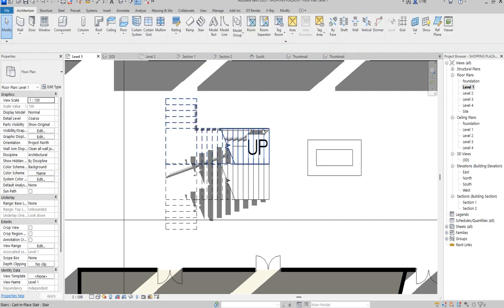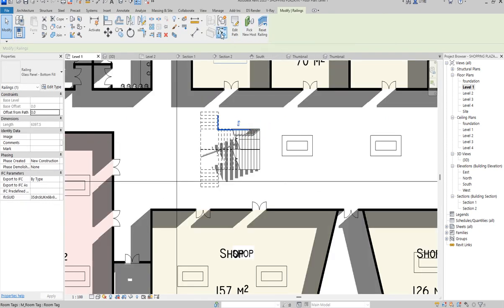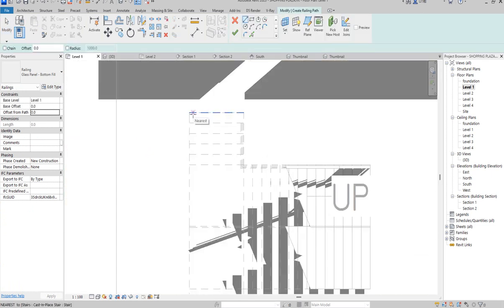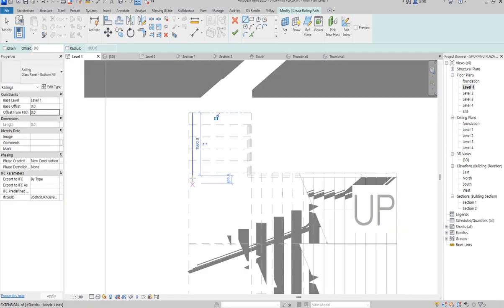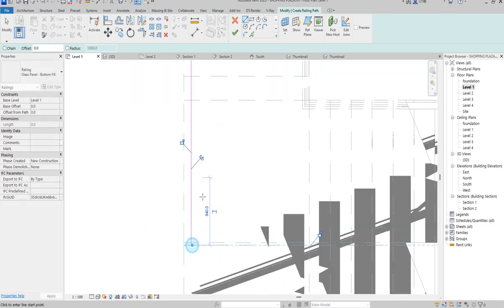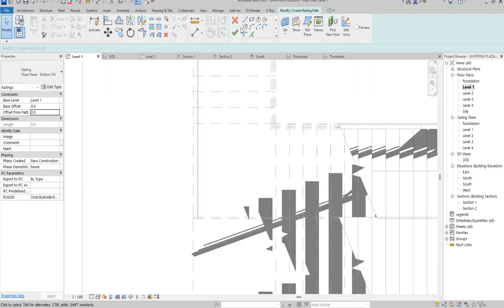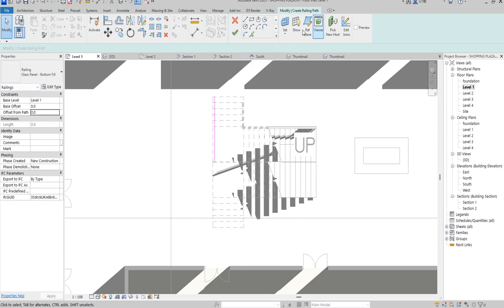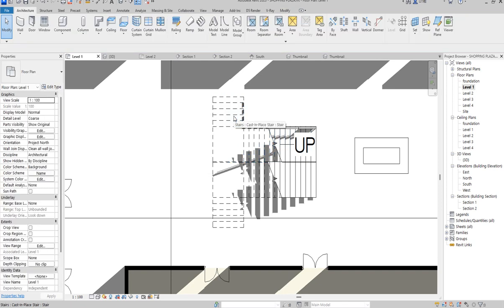That is the host. The same thing you do here by clicking railings. Choose the railing and say create similar. Do what you have done the way you did it here. When you get to this place, drop. You pick again. You can drop it here halfway. Then you click again and drop it here. So you have 3 things to work with. In fact, you can still create more and make it 4. As you have done it, just say click finish. Then you just say pick host.